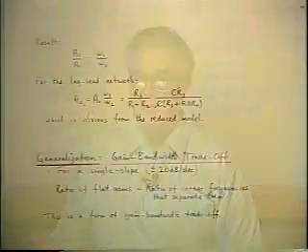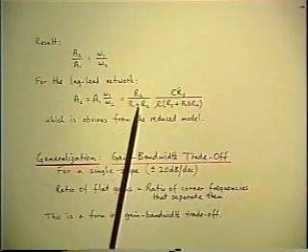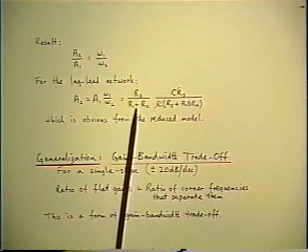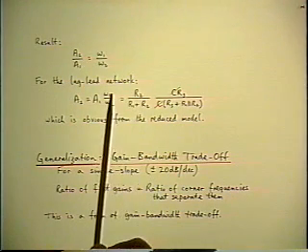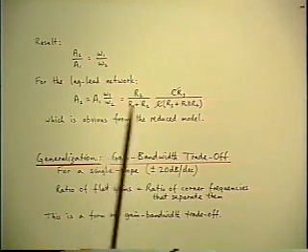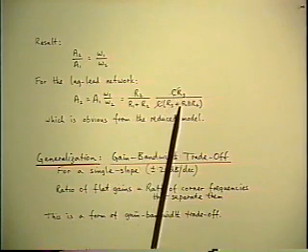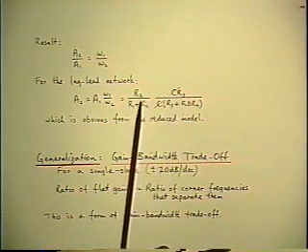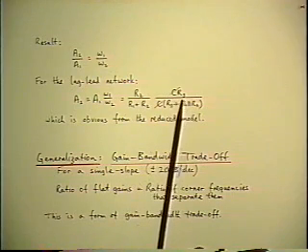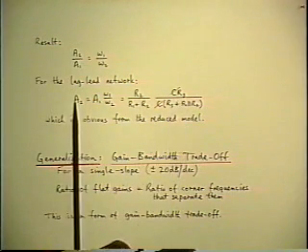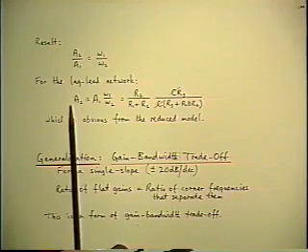In this particular case, it's easy to check that that ratio expression is correct, because A1 is the original resistive divider, and if you substitute for the definitions of the two corner frequencies, you get this ratio. The capacitors cancel, and what you're left with is the product of two ratios, representing the infinite frequency gain.